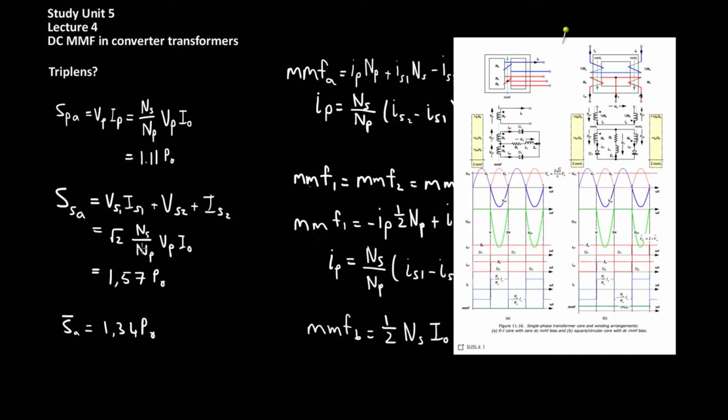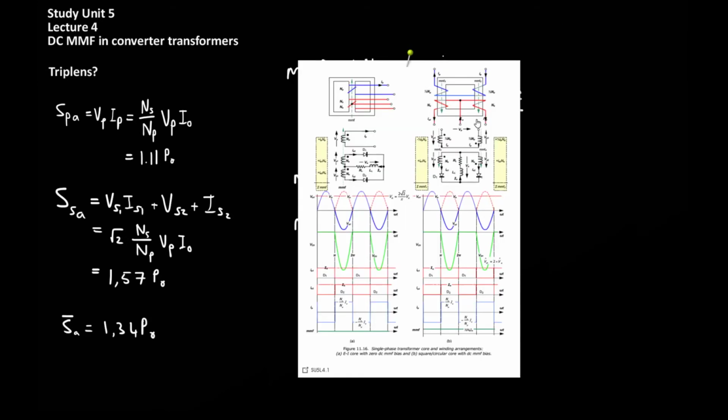These equations apply to both cores, so essentially on paper both cores have the same power factor, except the toroidal core has the undesired MMF bias. So what needs to be done is to find a way to wind a single toroidal coil in such a way that the DC MMF bias is 0. In this way, the advantages of using a toroidal core can be harnessed above those of using a laminated core.